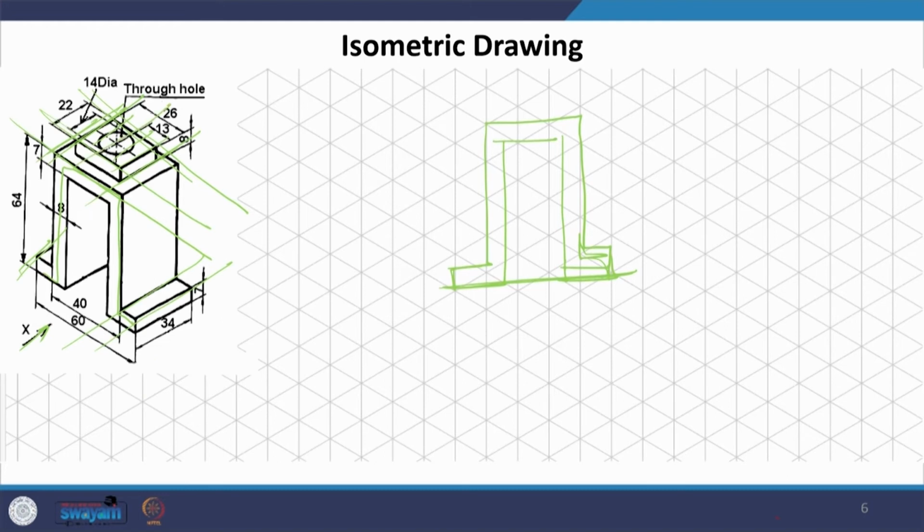What you have to do is the way we did in ortho to iso, identifying the reference planes and then drawing the iso. We will do the same here. In the iso, we will arrive at the parallel lines. Wherever the parallel lines are coming, we are very sure that these parallel lines, which are visible as parallel in the object in the isometric view, are going to be the same in the orthographic views as well.